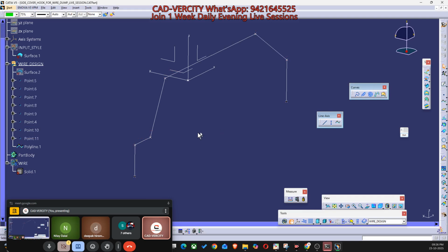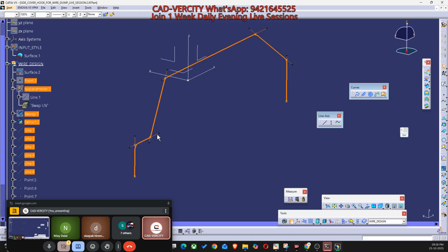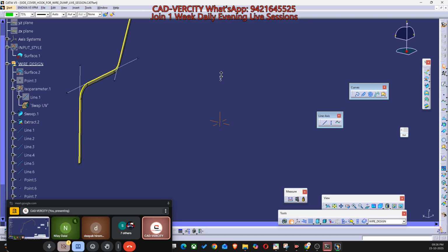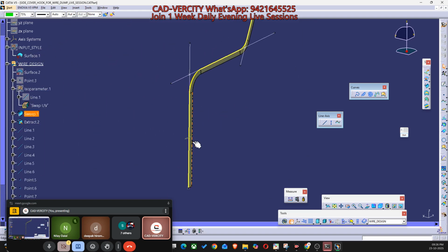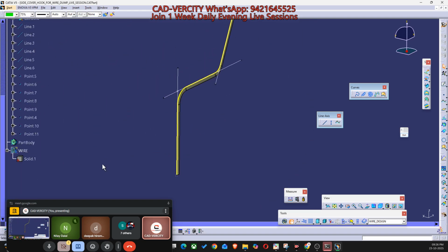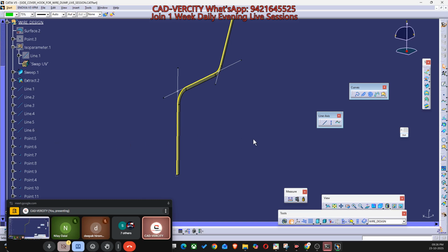Yes, sir. Okay. Before deleting, what I will do? I will say undo. Why? Because I need this surface, sweep surface. I will explain. Okay, before deleting, let's hide all lines, all curves: line hide, curve hide, surface hide.